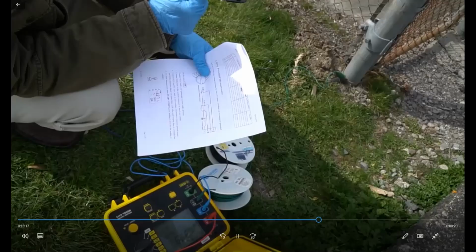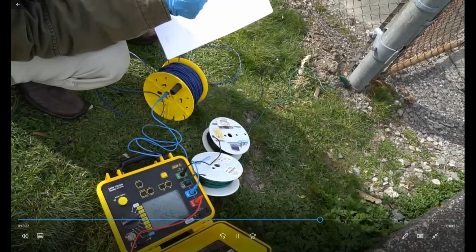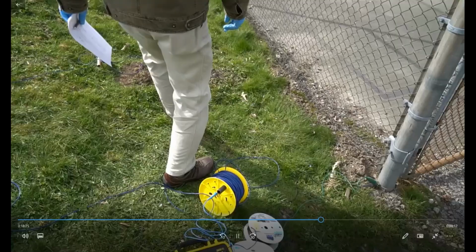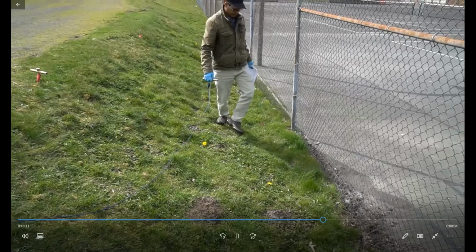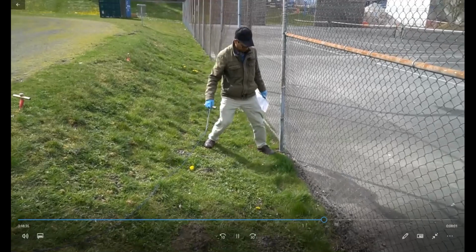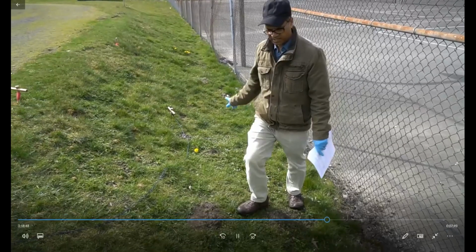We have to use this short circuit current and multiply, that will give us the touch potential. So this is one reading, and this way we will take some other readings in other locations. So we'll just pull this probe up, and again in another location 1 meter away. So the second touch potential measuring point is there. Again it is 1 meter away from the fence. We'll press the start button,